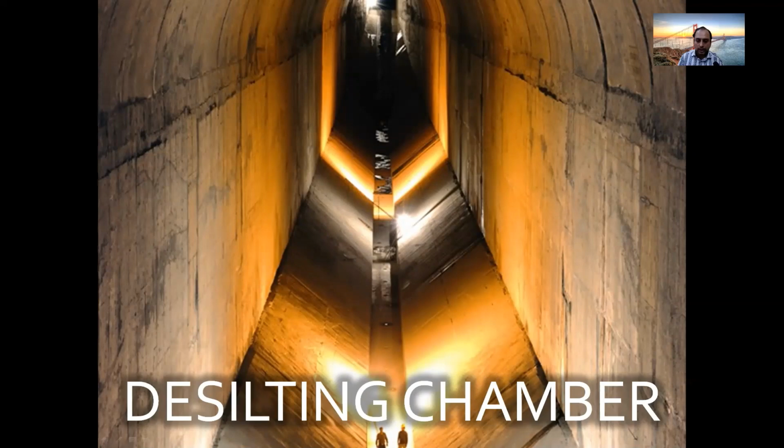If you can see, there are two workers standing here. So you can imagine the height. Okay, this is the tunnel, silt flushing tunnel at the bottom. So all the silt which is settling down will come here, slide through this, collect here, and will be taken out of the desilting basin. The clear water will go out from the desilting basin from the top.